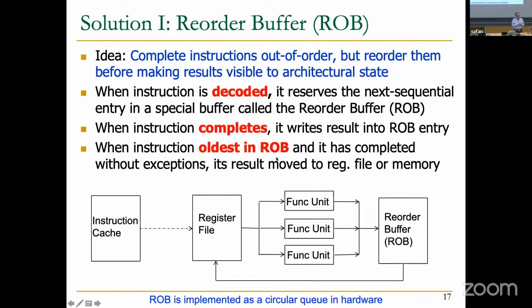But we have multiple functional units. If I have first a multiplication, and then I want to use that result in the next instruction, which is a simple addition. Then I have a problem, right? Because the multiplication hasn't finished yet, so I can't start the addition. Yes, and that's a problem of this pipeline. This is an in-order pipeline, right? So in an in-order pipeline, it is in order. We'll see how we can handle it soon in later slides.